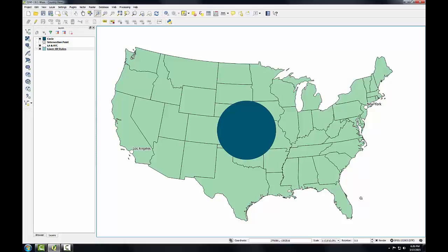There are many ways that we can customize a CRS. Any of those parameters that we saw can be customized. And you saw it only took a few seconds to create a new version of a CRS from an existing one. Often you'll customize a projection so that it's centered on the area in question, in this case the United States, simply by redefining the particular cartographic settings, such as the central meridian, the standard parallels, the reference latitude, or false eastings and northings. The choice of which parameters to change depends on which projection is being used. In Task 4, we'll explore state map projections.